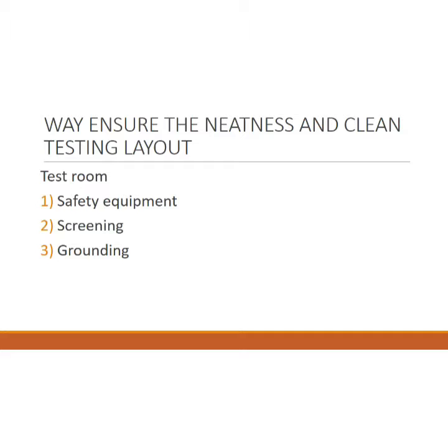The most important criteria of a good test room are screening and grounding. And the first is the safety equipment. The test area should be enclosed by a metal grid fence at least 2.2 meters in height with a maximum grid spacing of 40 millimeters. Second is screening.